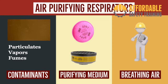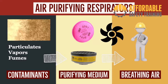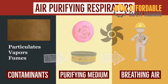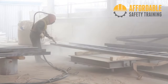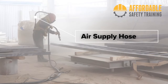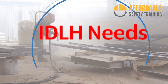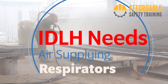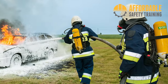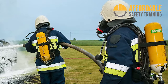Powered air purifying respirators use a motor to draw air through a filter. These respirators are easier on the user, and provide a higher level of protection. Air supplying respirators provide fresh air to the user from a clean source. They can be used in low oxygen environments. Air supplying respirators are required for atmospheres that are immediately dangerous to life and health. The self-contained breathing apparatus, or SCBA, is an example of a type of atmosphere-providing respirator.